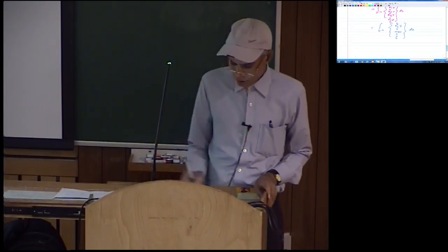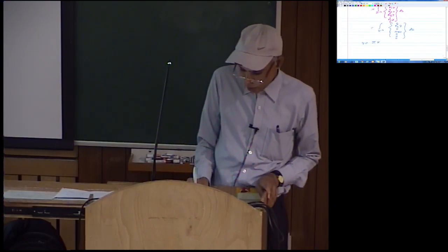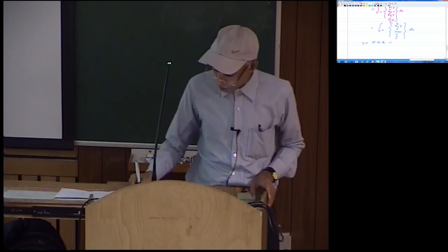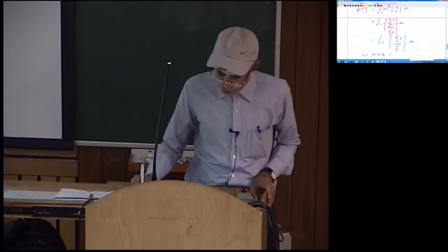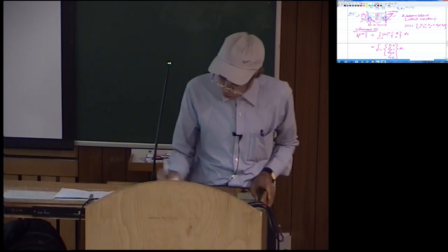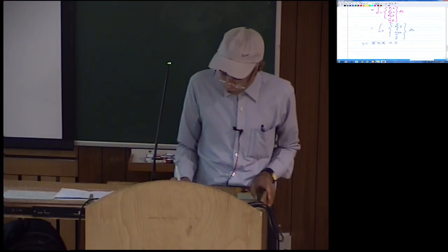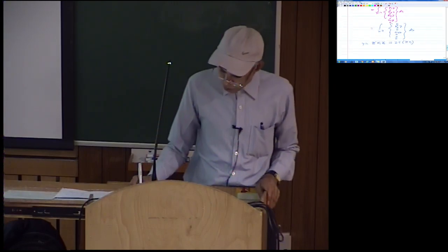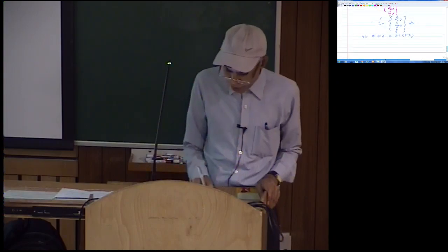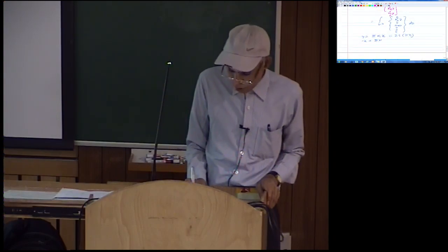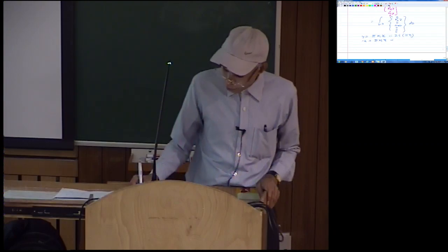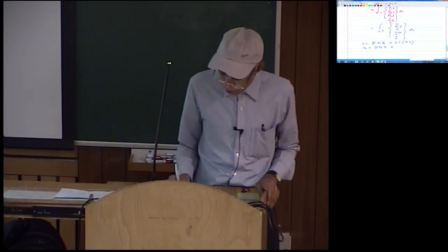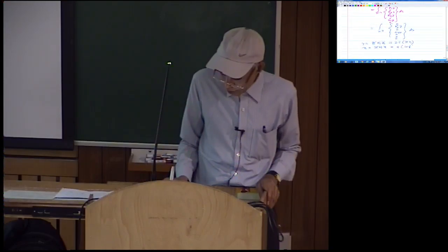So for that, y is equal to sum of Ni yi, and you will see that similar to the previous problem which I just discussed, the length of the element along the y direction is 5, so half of that is 2.5, so y would be 2.5 into 1 plus eta. And as far as x is concerned, x is going to be sum of Ni xi, and the element is a rectangle in the physical coordinate space, so this will be 5 into 1 plus xi.